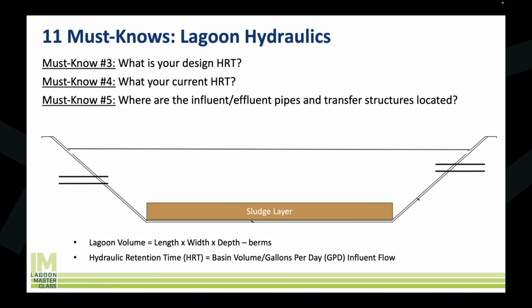What do you think that's going to do to your treatment? You've just cut the time in half. It's not going to work well. And so it's really, really important that you understand the sludge levels in your lagoon and how they're building and changing over time. Again, I have a whole entire webinar on lagoon biosolids.